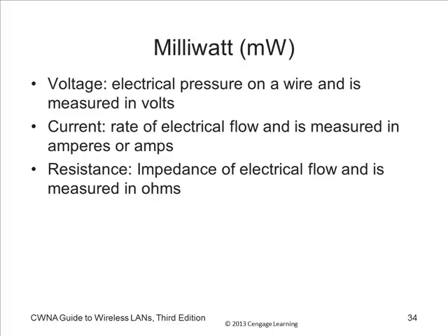Regular light bulbs, resistive light bulbs. Incandescent, yeah. They're resistive, aren't they? They've got a little filament in there that glows. Now, how much power does it take to run a 100-watt light bulb? 100 watts! How much does it take to run a 100-watt equivalent fluorescent? 13, 14 watts. You don't really have the heat issue. You get more efficiency.